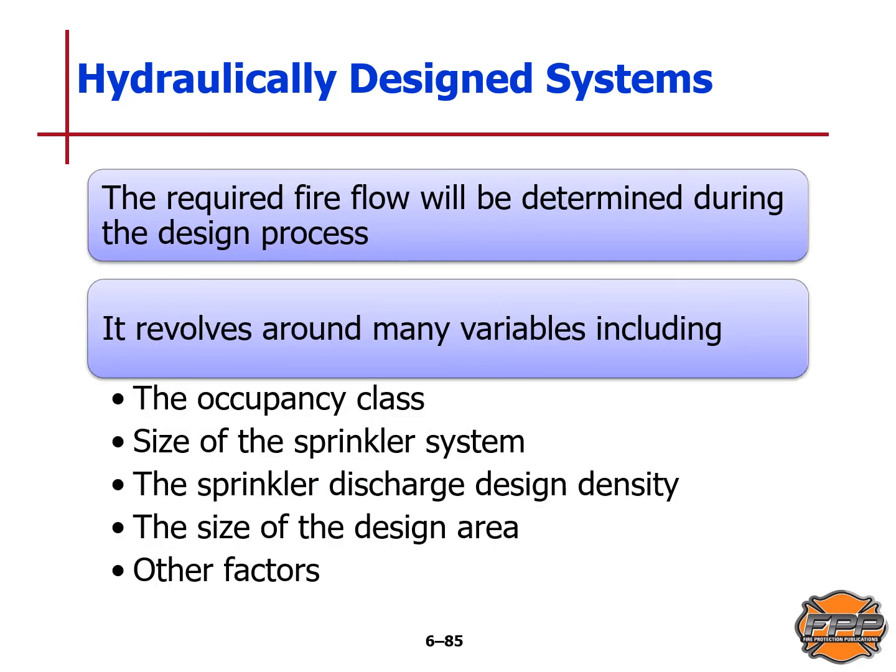In a hydraulically designed system, the required fire flow will be determined during the design process and revolves around many variables, as we mentioned, such as the occupancy class, size of the sprinkler system, the sprinkler discharge, design density, the size of the design area, and then other factors.